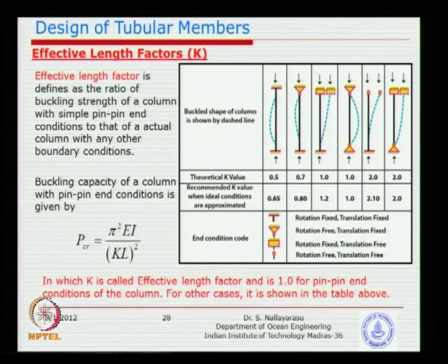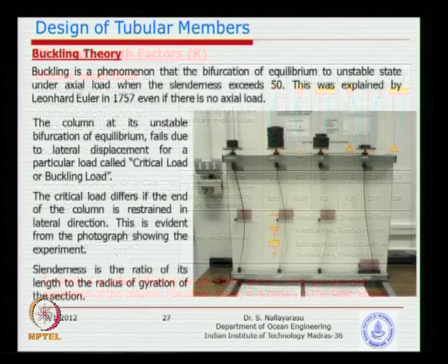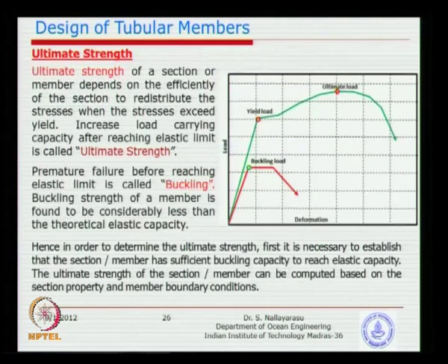So, that means the influence of the boundary conditions on the ultimate capacity, you see here you are going to increase the capacity, not allowing the system to buckle, because you make the system quite strong at the ends, fix it. So, you may reach slightly higher. For example, instead of pin condition, if I do a fix, it carries higher load than what it's supposed to be carrying with pin. That is the idea behind improving capacity by means of boundary conditions.